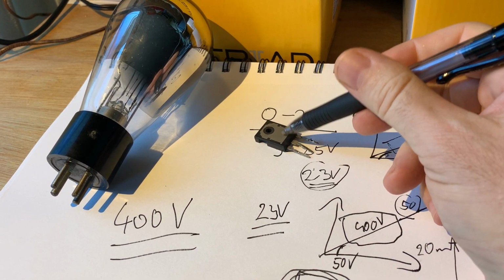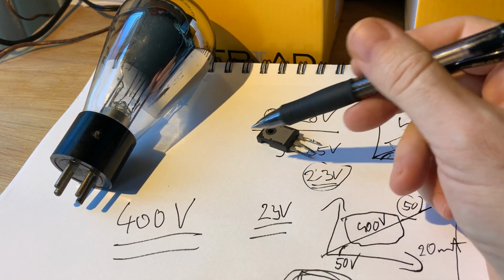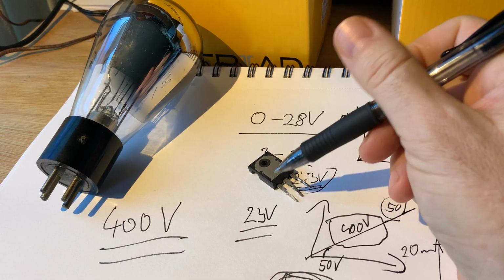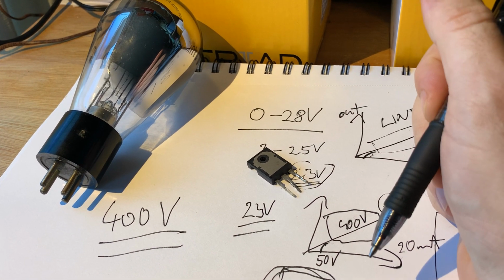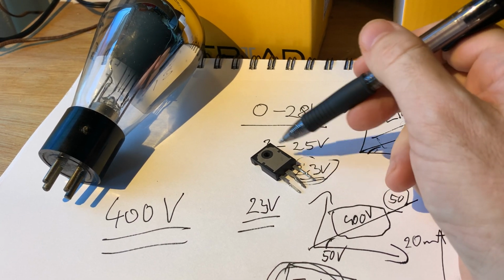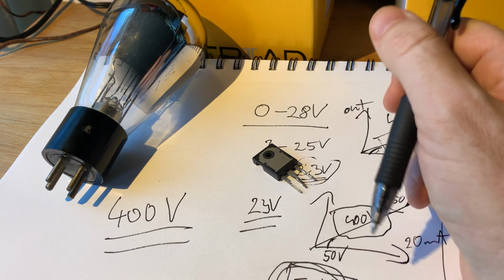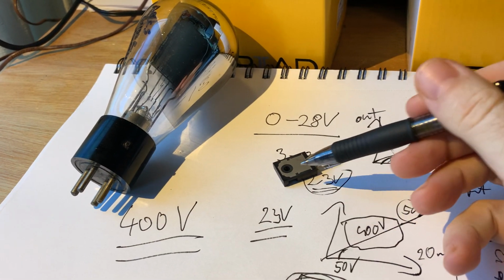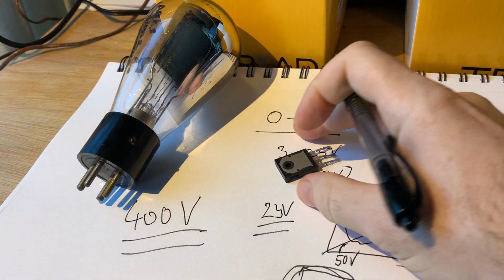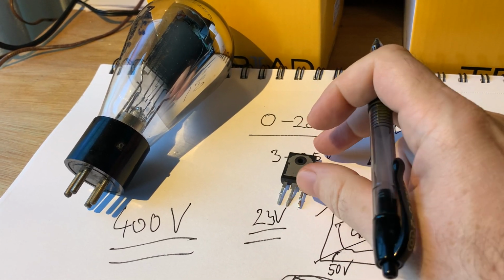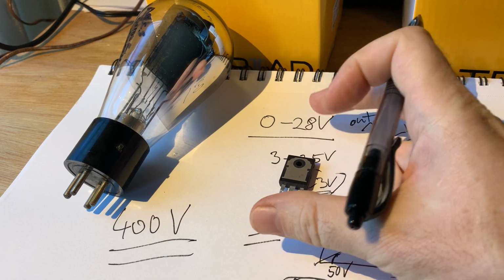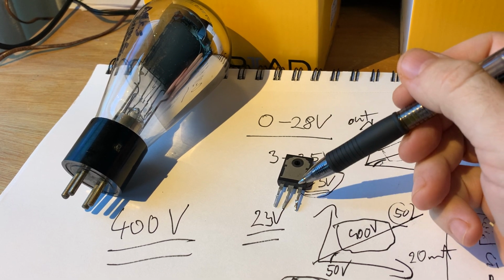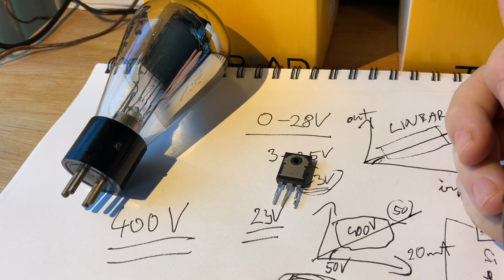The only changing that would be if we had a transistor running at 500 volts, but that costs much more than these tiny, low voltage transistors. That's why manufacturers are not using it, because the only reason the transistor came to being is the size. It is a fraction of the size, fraction of the weight, fraction of the cost, and that's all the niceties about transistor amps. If we want to increase this to handle 500 volts, then we would already be forfeiting much of the practical benefits that transistors give us.